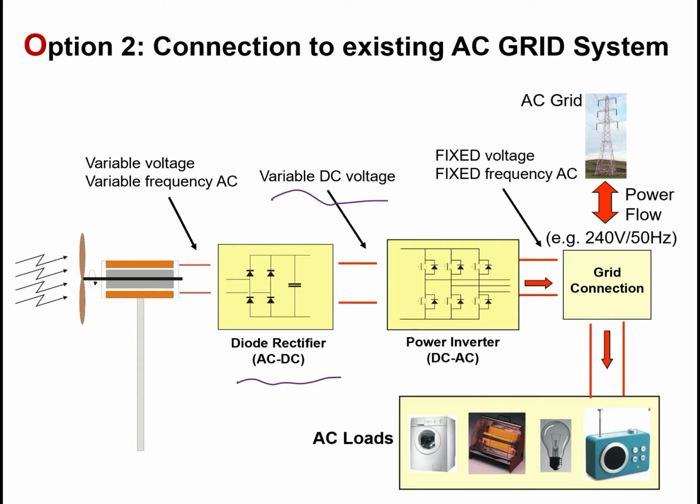So to supply the transmission network with power from these turbines, the signal must be passed through a power inverter, which ensures that the frequency of the voltage of the electricity being generated by the wind turbine is the frequency of the transmission system when it is transferred onto the transmission system.